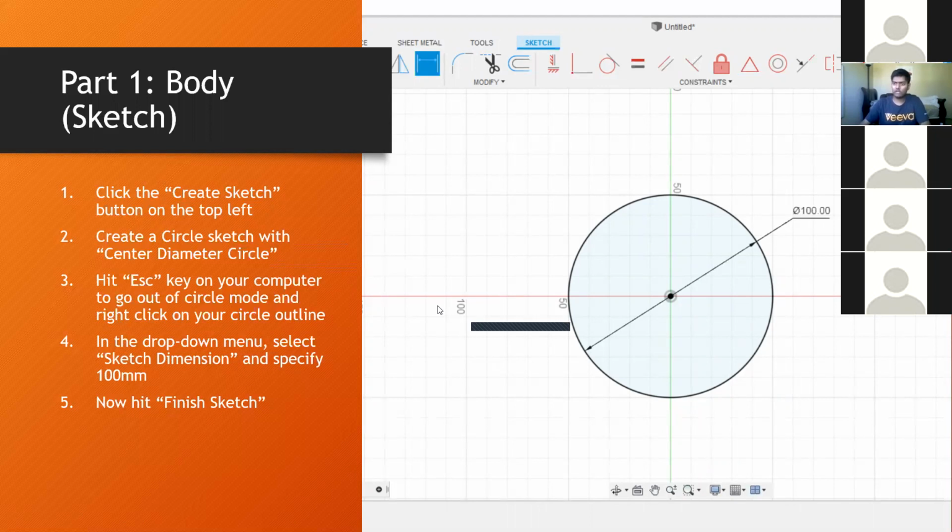So if you guys don't have access to a standard mouse, you can use this doohickey here to navigate your drawing. And also you can use the plus and minus tool here to zoom in, zoom out. But I highly recommend using a mouse regardless. So that's going to be our first tool, and to get out of any tool that we're using, any mode, simply press escape and you'll go back to a regular cursor.